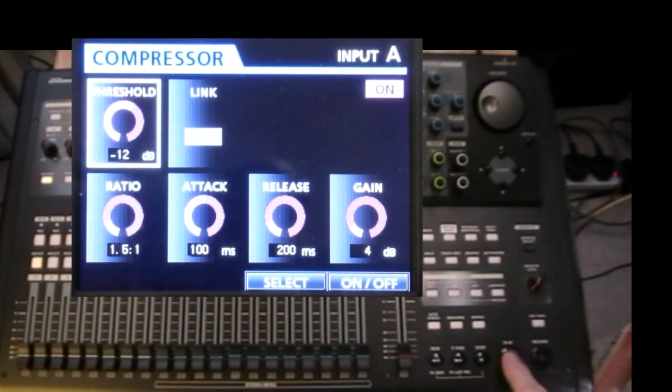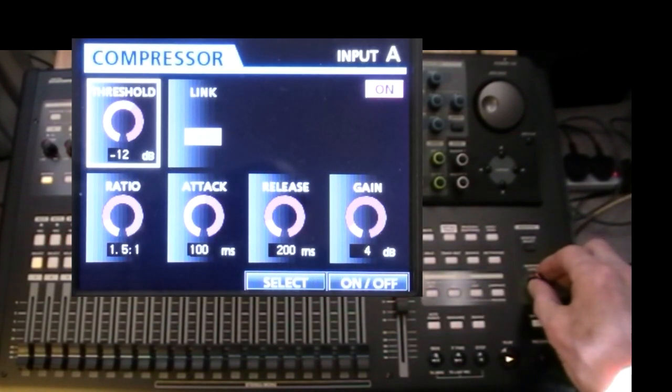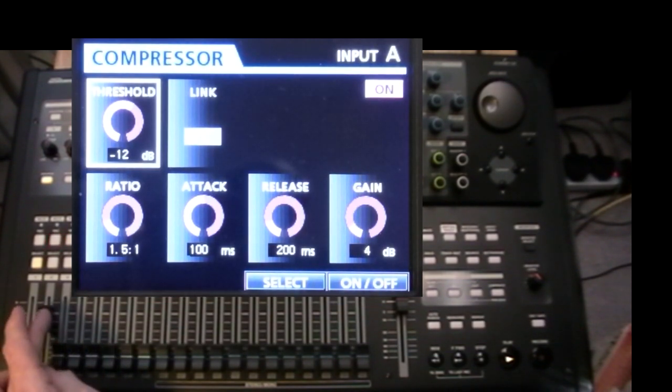If you press play, turn up the stereo fader and the monitor knob, you can use track fader 1 to play back the original uncompressed signal, and track fader 2 is the compressed signal. So you can compare with and without the effect and tweak the settings as required.